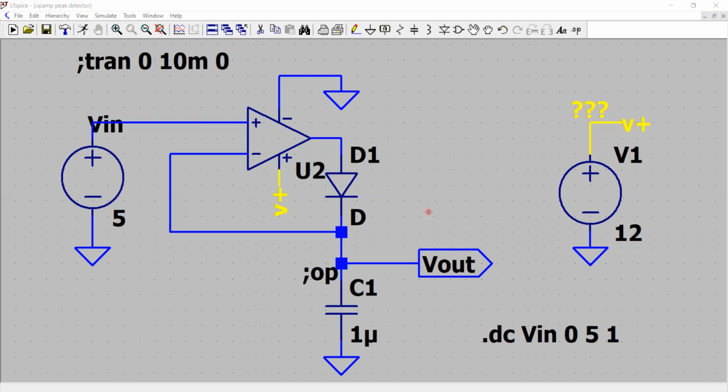Okay, and then after some time it will start discharging. But in the moment, if you still have a greater voltage at the positive that goes up more than the voltage at the negative, again the diode will be forward biased and the same cycle continues. So why not run a simple operating point analysis first, assuming you have this DC 5 volts, and we'll see what voltages and currents are there.